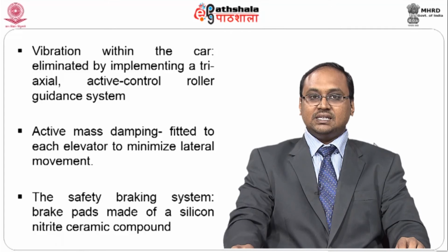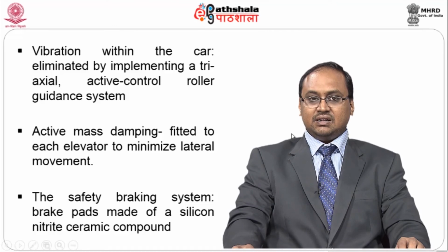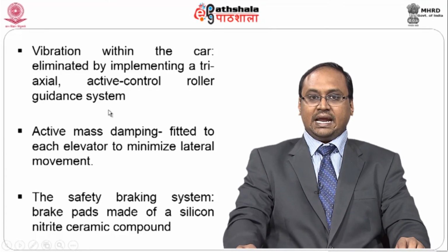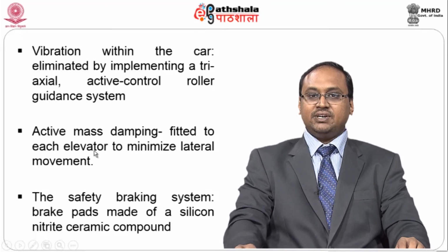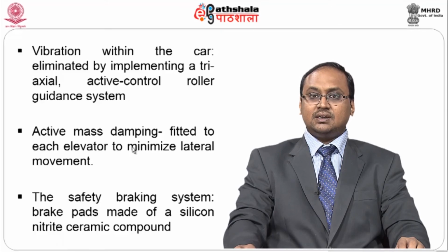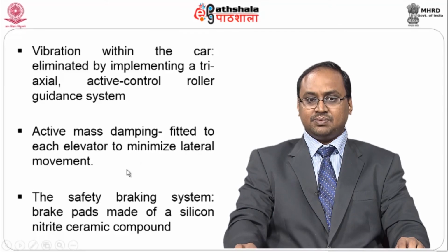So, the various challenges that are faced are such as vibration within the car. It is eliminated by implementing a triaxial active control roller guidance system, with active mass damping fitted to each elevator to minimize lateral movement. So, there is lateral movement as well as axial movement which needs to be taken care of. There is an equally important necessity about the braking system. In case of an eventuality, brake pads are made of silicon nitride ceramic compound for the safety braking system.